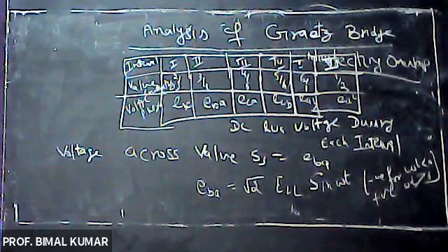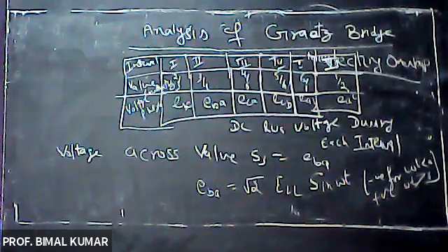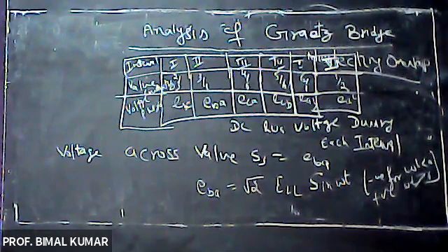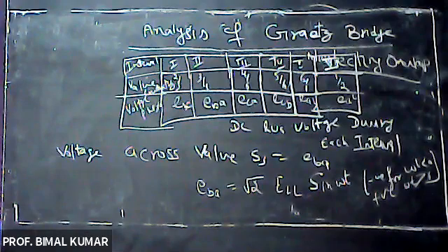Fine. So when omega t is less than 0, this EBA is negative, and when omega t is greater than 0, it will be positive, right? So if we are considering this voltage EBA with a delay angle alpha, as we have taken in that timing diagram, alpha plus 60 like that.